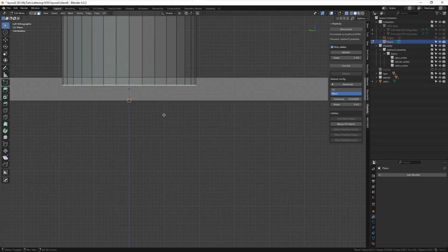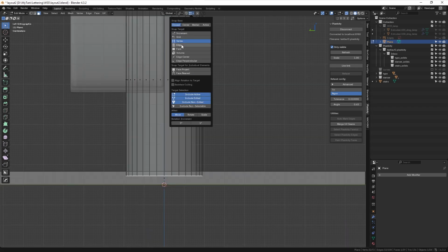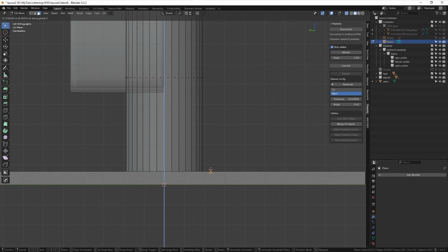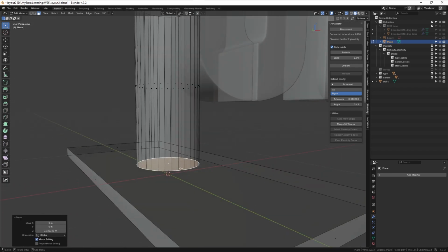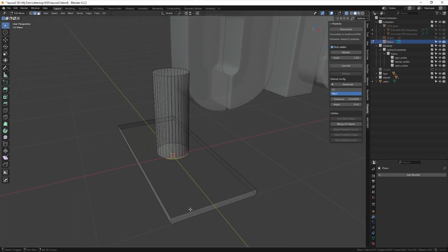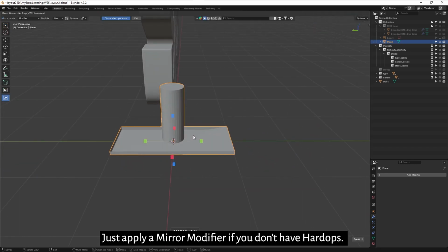Let's look from the left. Here go again to medium point, and here go to edge snap. So G, Z, and let's press Ctrl so it snaps to this edge. And we can delete this face pressing X, F. Let's select 8 edges and connect them to here, pressing F. We can do the same for the other side, pressing Alt X.